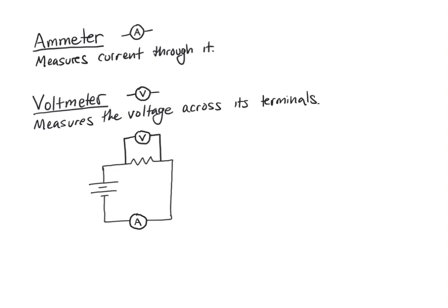There's actually more freedom than this though, right? Because the potential at this point is the same as the potential anywhere along this open section of circuit. And so I could actually connect the right side of this voltmeter anywhere to the right side of the resistor until I reach the battery. Same with the left side. I could slide this around anywhere over here.